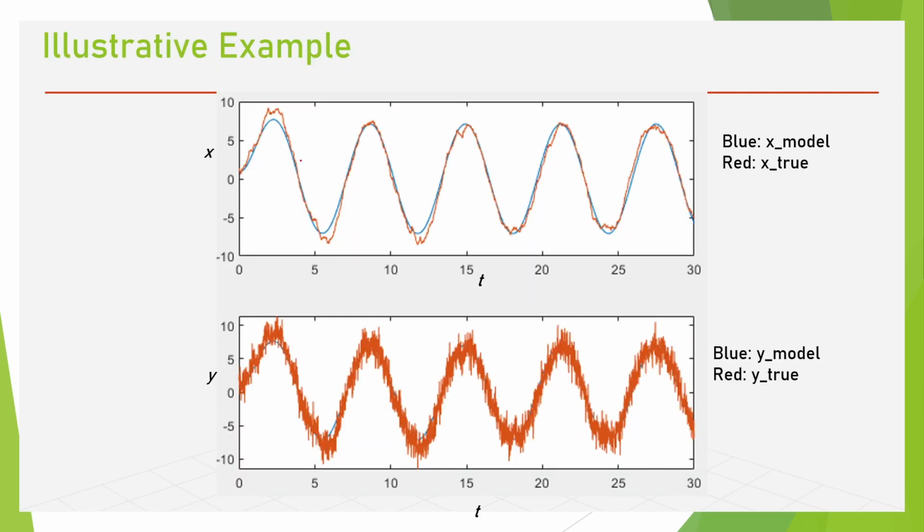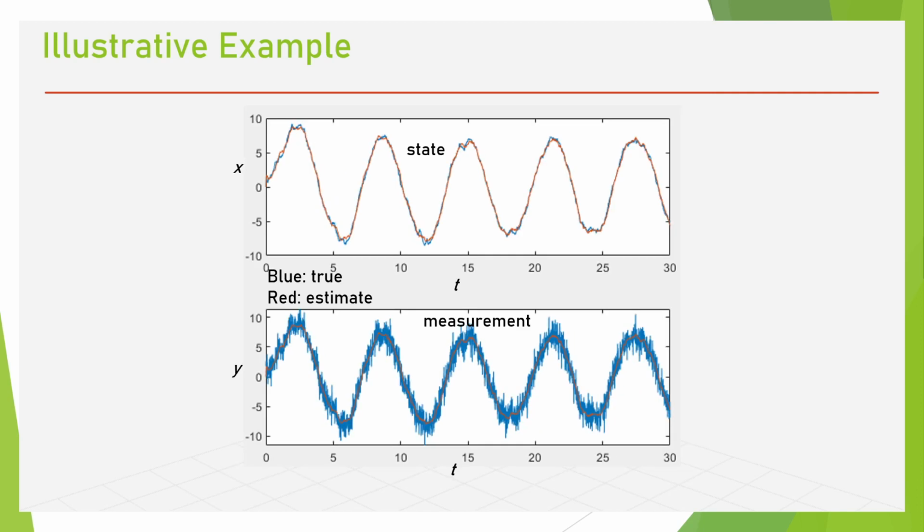Yeah, again, from that model, we compute the deterministic blue one, and the orange one represents the true state. Here, we want to measure h directly, but the sensor tells us with some noisy data. And then when I apply the Kalman filter, because the Kalman filter tries to estimate the true state, here the blue is the true state computed from the stochastic model, and the orange one is obtained from the Kalman filter. So it's very close, like this.